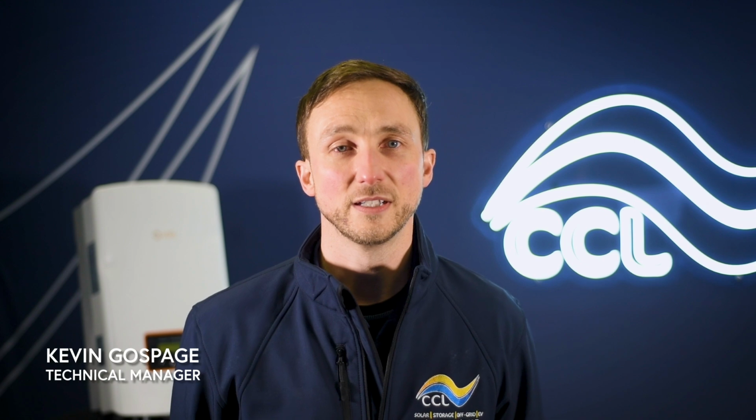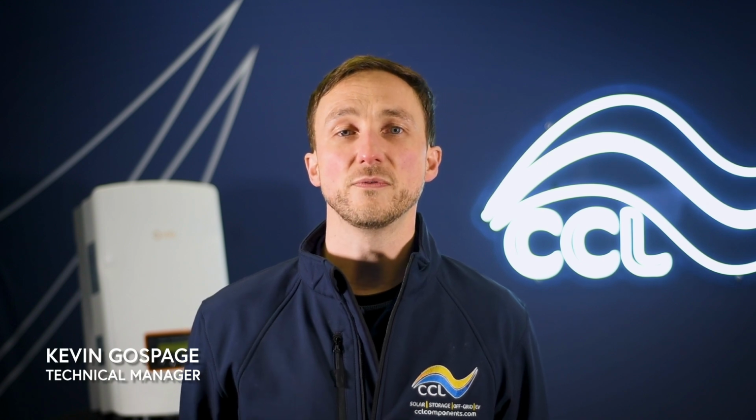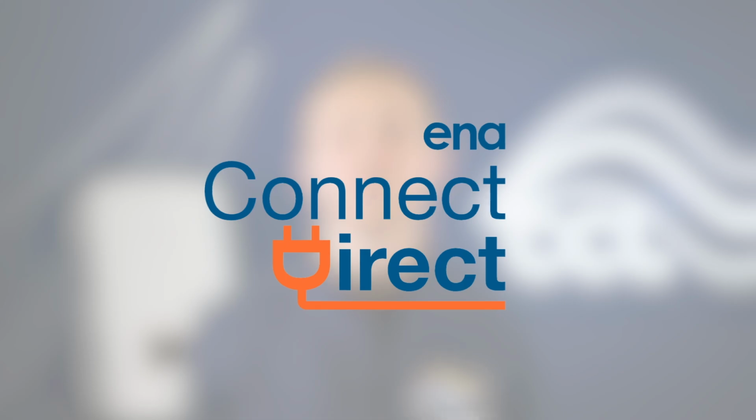Hi everyone. Have you ever been in a situation where you faced delays on a project because you didn't check if your inverter or grid-connected device had met the correct DNO requirements? Today, we're diving into the ENA Type Test Register and explaining how to find devices appropriate for UK installation. Along with your specific site details, this database contains the additional information needed to complete your DNO application forms.